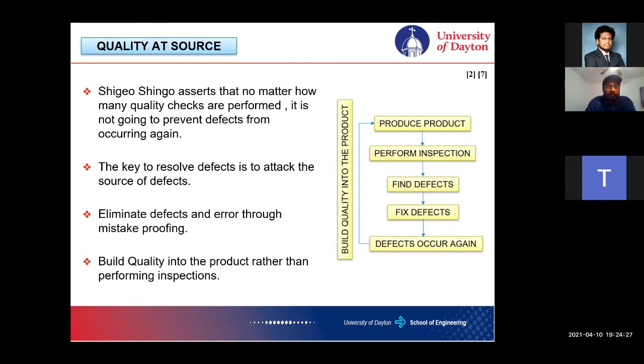Quality at the source is a lean manufacturing principle, which states that the quality output is not only measured at the end of the production line, but at every step of the productive process. In a practical sense, it would involve each operator checking his or her own work before the part or component is sent to the next step in the process. And if there's a defect, it can be communicated by the installation of andon lights to signal that there's something wrong in the production line. Each worker must check his work and ensure that the product that he's sending is defect free.